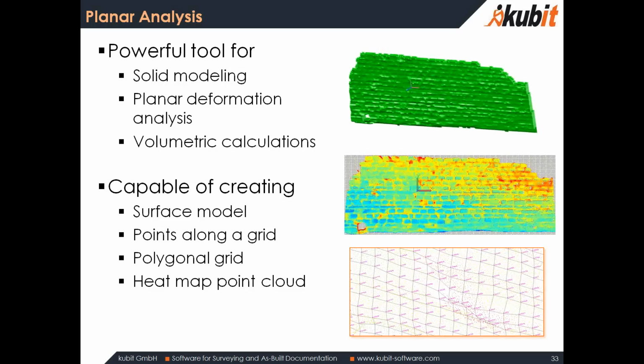And one of the ways that it really helps actually is for Civil 3D users, because if you're trying to use a point cloud to create your surface tins or your DTMs, I'm sure you've noticed that they're very heavy and it slows AutoCAD down quite a bit. But if you do this right here and create a grid of points, you can use those points, add Civil 3D properties to them, and then add those to a surface, and it is much lighter, and you still get the exact same result.